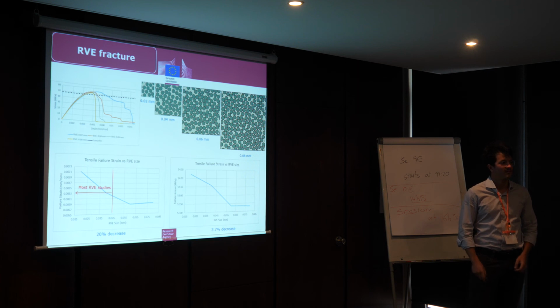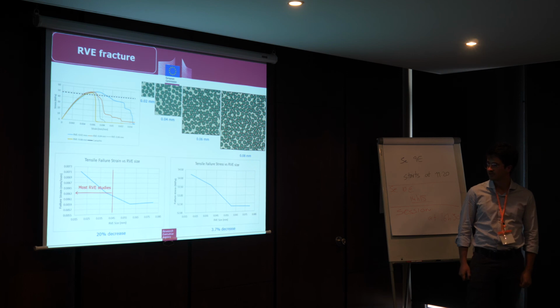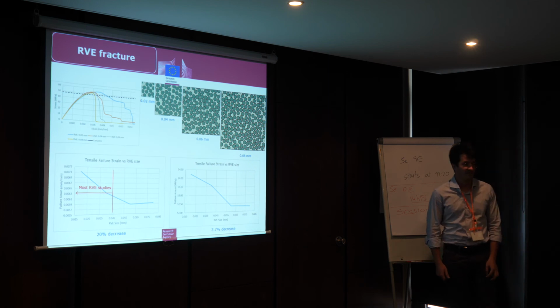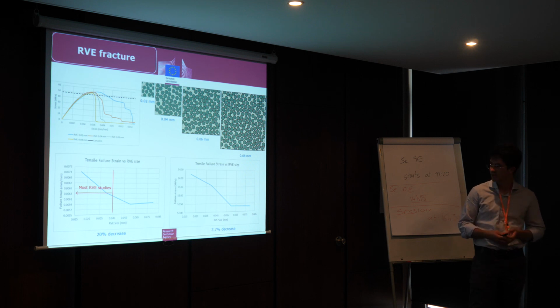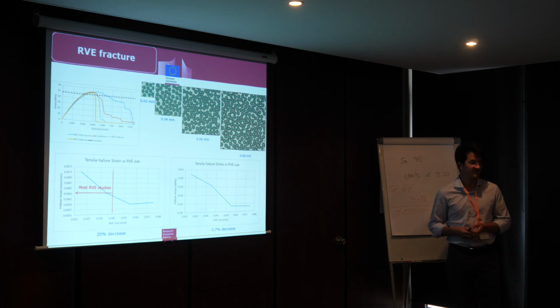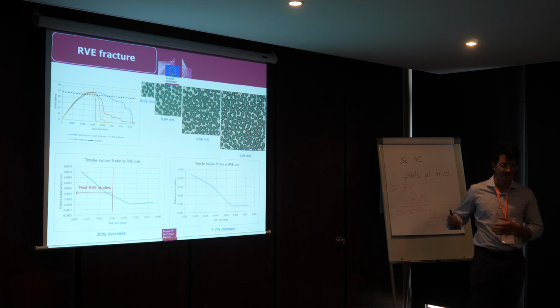Yes, please. And one question, thanks for the presentation, very nice. You're using a von Mises plasticity, so did you also think about maybe some compression, tension, anisotropic kind of model? Yes, I'm actually working on that. I'm testing a few other plasticity models that account not just for the deviatoric, but also the volumetric part. The problem right now is convergence, so that's why I haven't got this kind of comparison with those models.